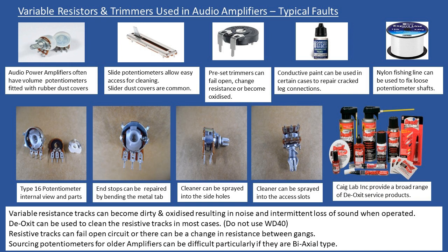The next one is these preset trimmers. On the previous audio tutorial that I went through, I talked about silent killers, which seems a little bit of an extreme language, but these things are typically used for adjusting DC offset and, most importantly, the bias within audio amplifiers. When they fail, you have an output stage failure, these resistors just burn out, and there may be no physical appearance of anything untoward, but you need to remove them and measure them and ensure that they're not